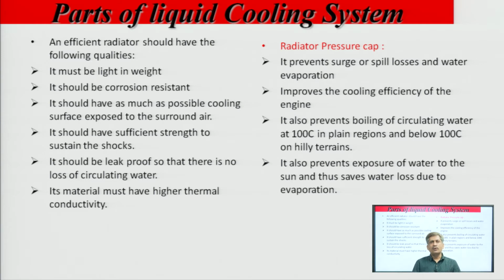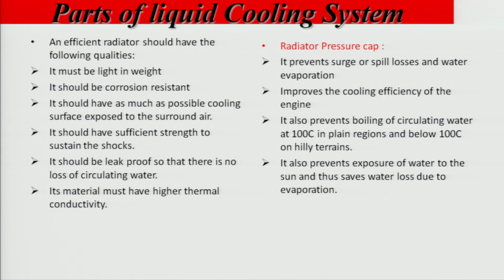Steam will be formed after boiling of the water, and this is not desirable, as it resists the flow of water inside the hose pipes. So, why is the radiator pressure cap used? It prevents surge or spill losses and water evaporation, and improves the cooling efficiency of the engine.